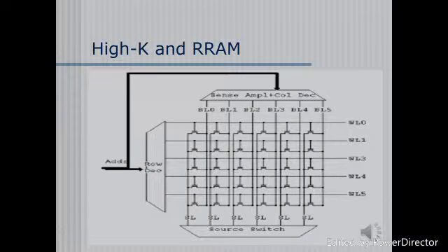Silicon oxide and nitrogen oxide are used in stacks between the storage floating gate and the top control gate as inter-polysilicon dielectrics. Currently, the polysilicon wraps itself around the floating gate, where the sidewall overlap adds to the capacitance that is sandwiched between the top control gate and the floating gate, giving the critical coupling to have the device work.